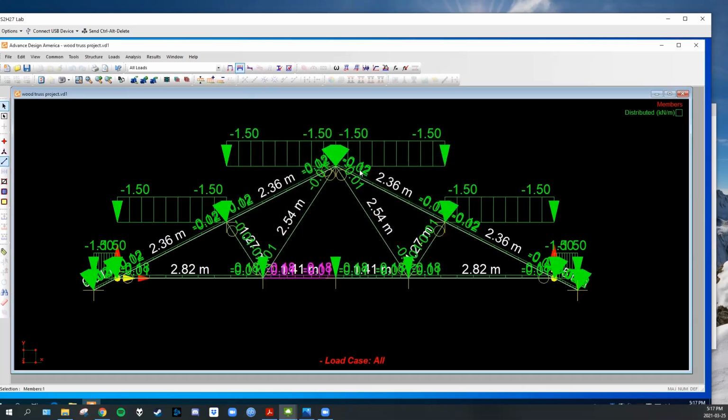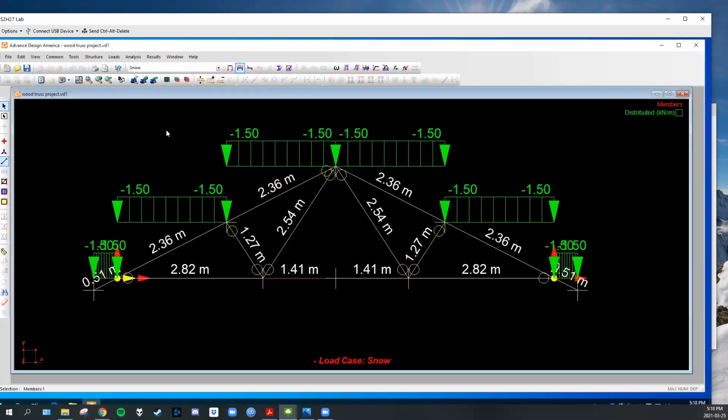Now let's start with your snow loads. Okay, just do one at a time. Your snow loads are perfect, right? Because that's what it's supposed to be: 2.5 times 0.6 gives you 1.5. Yeah, that's perfect. So take off your snow loads. Let's go to your superimposed dead loads.